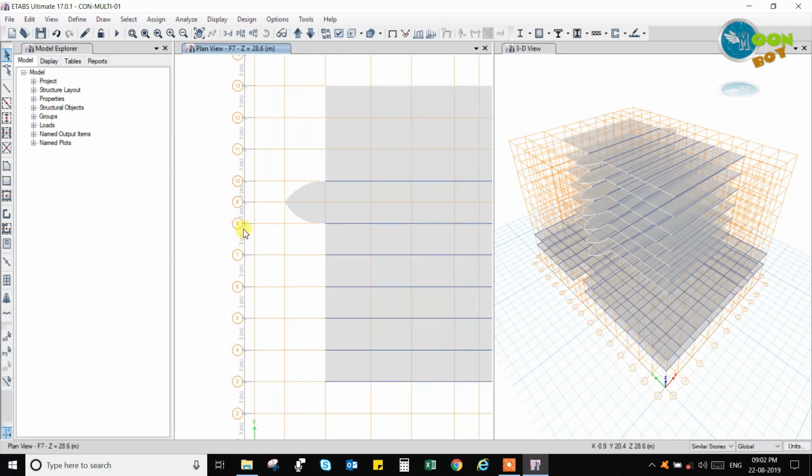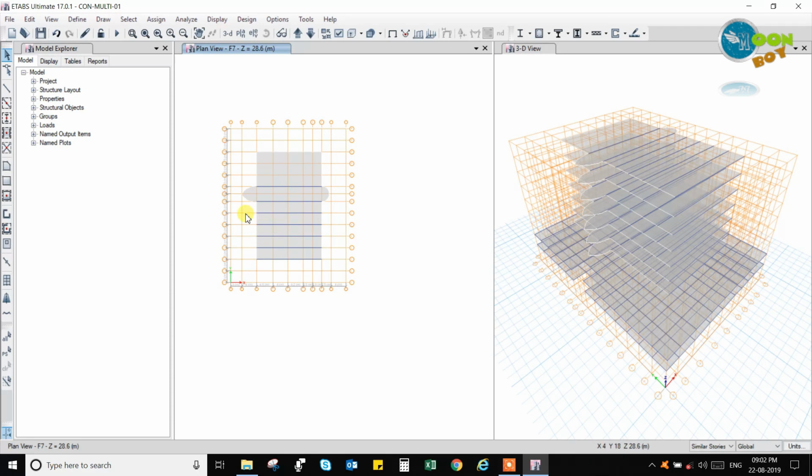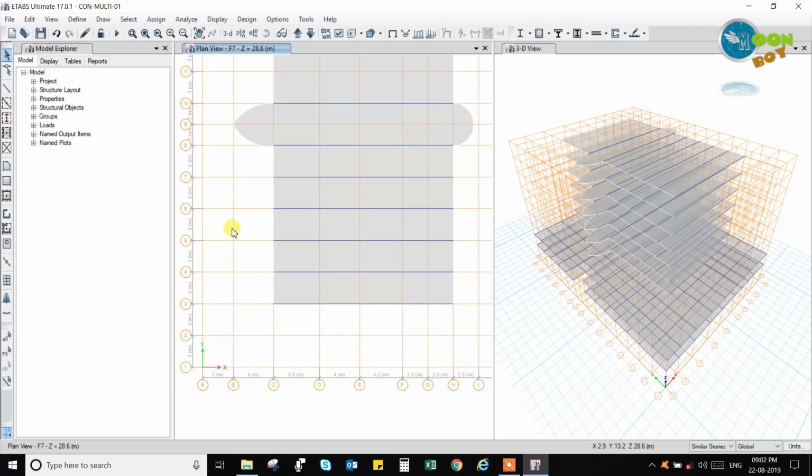So before selecting the depth of the beam, you have to see what sizes of frames are available in the market, and based on that you have to give the design of the beam depth. You subtract the slab depth from the beam bottom, so you will get the beam sides, and the beam bottom will be the size of the bottom, that is 230 what I have taken. So you have 230 board and 300 board. If you are using plyboard, it is up to your design. They will cut the sizes of the ply, and they will do the shuttering in the plyboard, any size they can make.